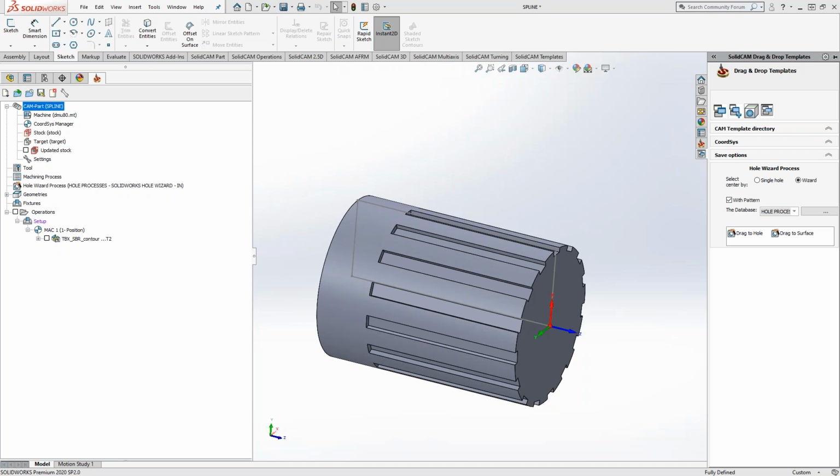So, wanted to follow up with something that we mentioned yesterday. Kevin had mentioned that we were working on a unique application for a customer where they wanted to be able to do splines on a mill turn machine. And I had created a part previously, and I found it, so here it is. Essentially, all this is using the broaching toolpath from our toolbox cycles on a mill turn machine, and how we would simulate that with the tool being basically mounted on a turret.